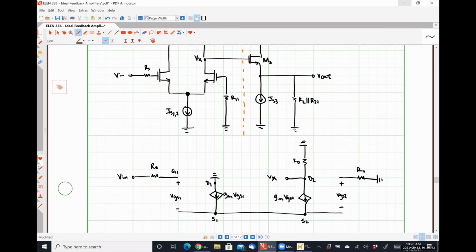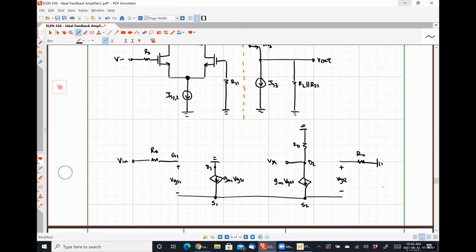Everybody okay? Everybody see anything wild or crazy? I am going to do something here that's going to help with our analysis a little bit. I'm literally just going to say that there is some voltage here at this node, Vs, with respect to ground, okay? Because we know that voltage could be 0, but it isn't definitively 0 because our first stage is not symmetrical.